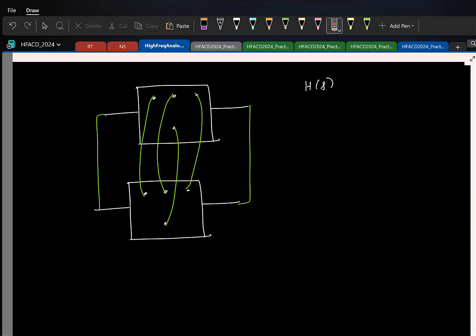So if I do that, see, these are identical circuits. So if I apply some signal here, the node voltage here and here are going to be same. So even if I go and connect it, nothing is going to change. That's how we are making sure that the transfer function also doesn't change. Right? So if I have a resistor R in the original network, after putting two of the networks in parallel, what will happen to the effective R? R by 2. If I have an inductor connected somewhere, L by 2. If I have a capacitor, 2C, and if I have an OTA, some GM, 2GM.